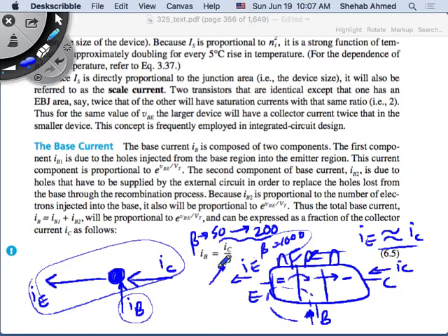So what does this mean? That means I have to keep pushing 1 amp continuously, right? If beta is 1,000, and we said this is a special case actually. If IC is 1,000 amps, that means IB is 1 amp all the time. Can you imagine 1 amp is continuously having to be pushed through the base for you to push 1,000 amps through this device.